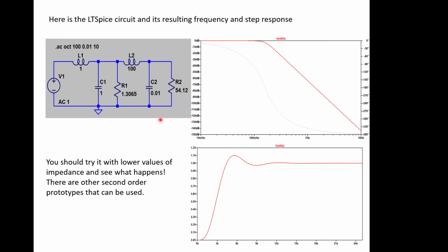So that's something you can do, and if you get some time you could actually put this circuit into LTspice and then try impedance scaling the different sections, because you notice I made it 100, and see what happens when you get the impedance or loading effects a bit wrong. That's the power of the simulator. It's also the power of knowing the maths and also understanding a little bit about impedances. So have a play just to get a feel for it.